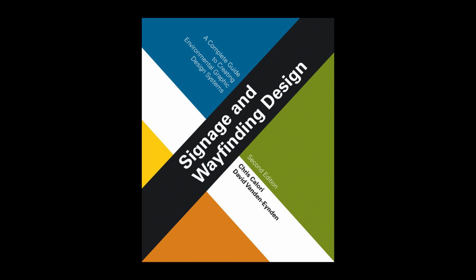unit, such as its sign type, if it's not a component of the sign number, message, including arrows and symbols, plan drawing number, construction drawing reference, if applicable, mounting drawing reference if applicable, graphic layout reference if applicable. Most message schedules also contain a remarks column for tracking such items as changes, additions, deletions, signs for which client inputs is required, and so on.